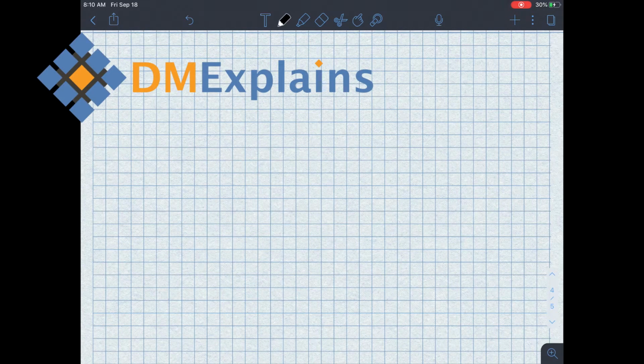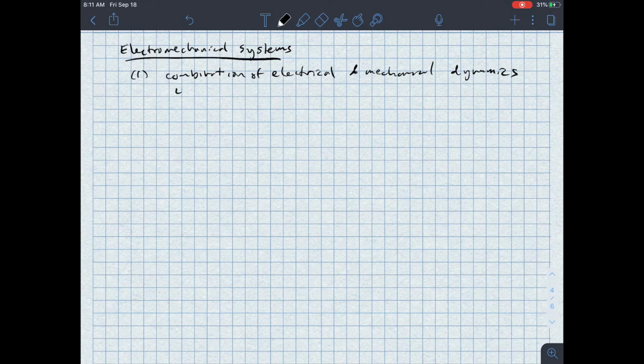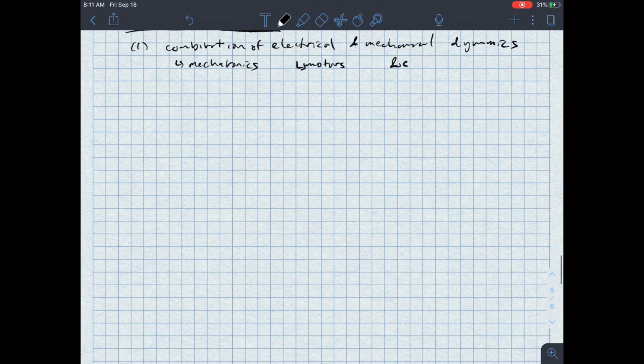In this video, I'm going to talk about how to model electromechanical systems using the Laplace transform. Electromechanical systems are the combination of electrical and mechanical dynamics. These include mechatronic systems, motors, generators, and a whole host of other types of systems. One thing that we should note is that typically electrical dynamics happen much more quickly than mechanical dynamics, so sometimes we're able to ignore our electrical dynamics.